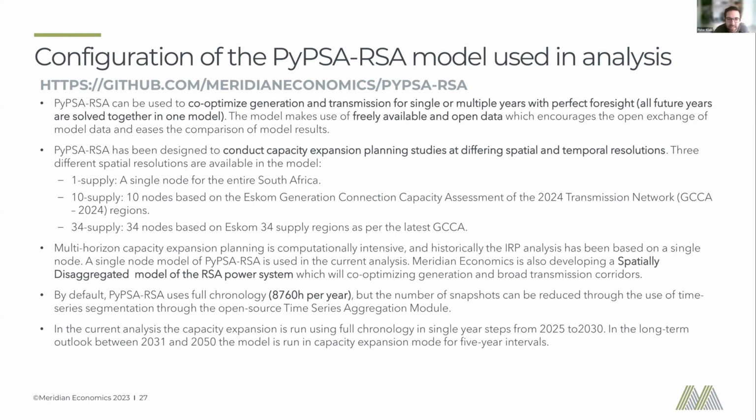So if you tell the model that instead of every hour in the year, you want every third hour, one easy way would be to just work out averages. But what the TSAM segmentation function allows you to do is work out, based on your load and different generator parameters, where your highest gradients are likely to be. And it puts more hours in those high gradient regions. And when the gradients are a bit lower, then it averages those snapshots together. So you can think of it as a smart averaging.